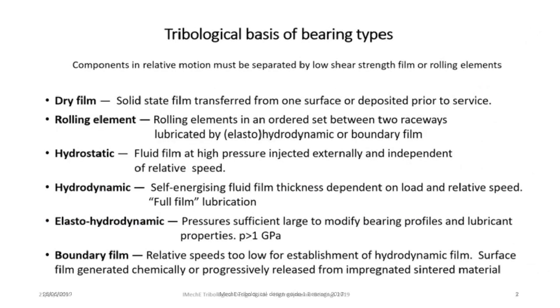In any bearing, it's important to physically separate the opposing materials of which the moving components are made. If unprotected sliding metals come into contact while carrying a load, friction and wear levels are likely to be unacceptably high. In the simplest form of journal bearing, the shaft or journal rotates without additional lubrication within a sleeve or bush, often made of some sort of polymer. Protection comes from a very thin layer of the polymer, PTFE is an example, that is transferred from the bush to the shaft.